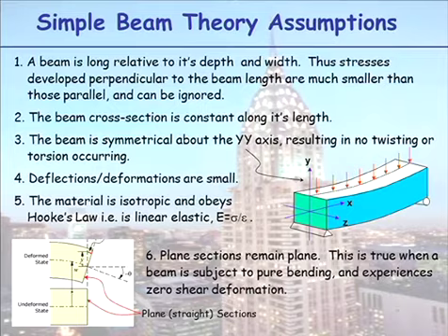The material has to be linear elastic and isotropic. It has to obey Hooke's law, and we have stress over strain is equal to Young's modulus. And finally, plane sections remain plane. That's all I'll say about that now, and we'll elaborate on that in second year.